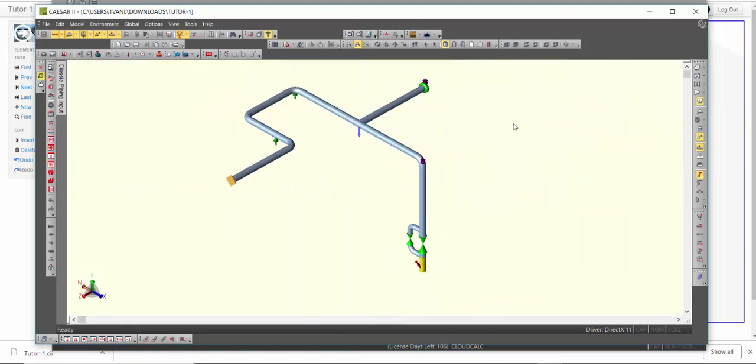And there we go. The only difference here is you may, once you get back here, want to change this back to a WRC 297 nozzle, but everything else should be intact. There's your concentrated load, there's your new spring, there's the new elements that you put in, the flange, etc. And that's it. As easy as that.